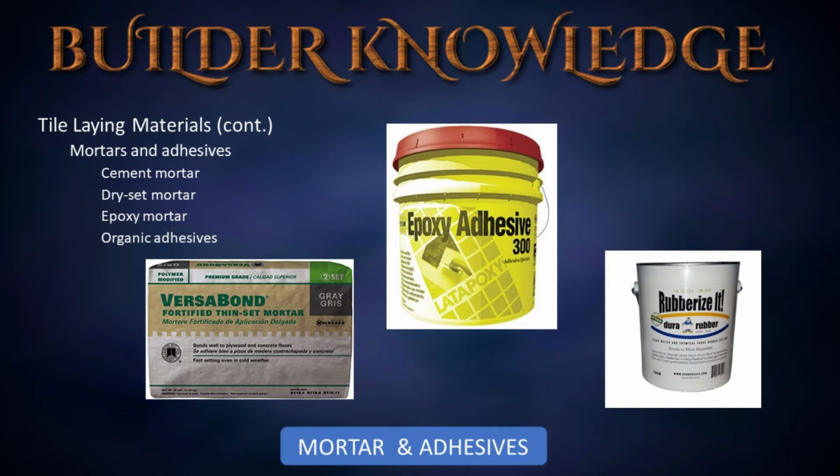Epoxy mortar is an epoxy resin and hardener that is mixed on the job site. Once the parts are mixed, the pot life is about 1 hour, depending on temperature. It may be applied over bases of wood, plywood, concrete, or masonry, and has excellent resistance to the corrosive conditions often encountered in industrial and commercial settings. Epoxy mortar is non-shrinking and non-porous, and provides a bond strength of over 1,000 pounds per square inch.